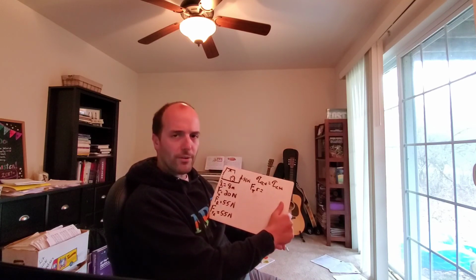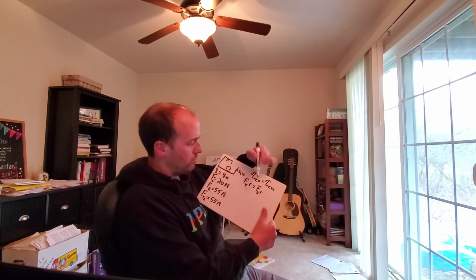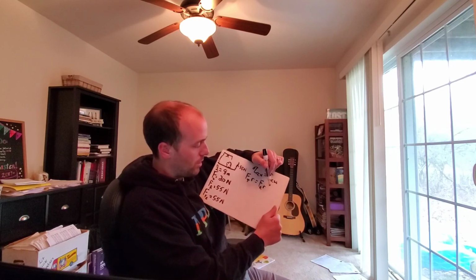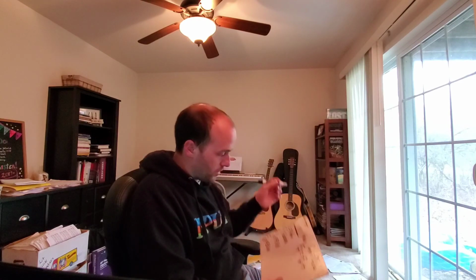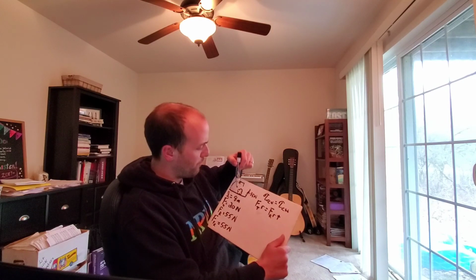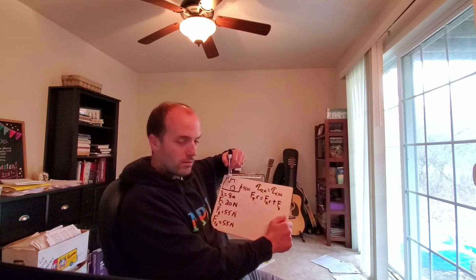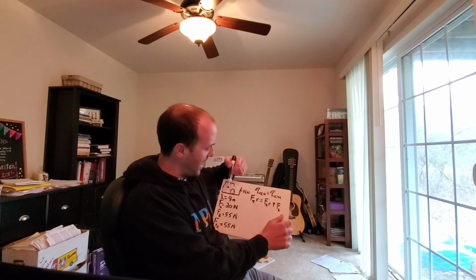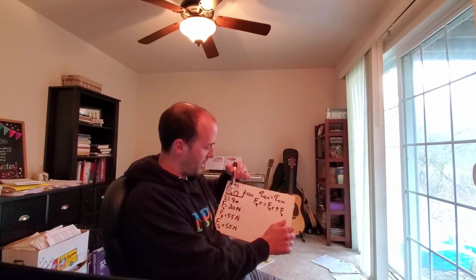We don't know where that rock is, so it's the force of the rock times our unknown moment arm. This is our unknown. Plus, because they're both causing a torque in that same direction, the weight of the beam. Now again, the beam's force acts at the center of mass, so that is the moment arm for that.